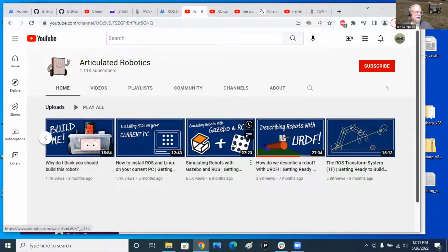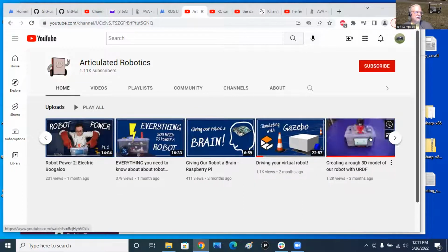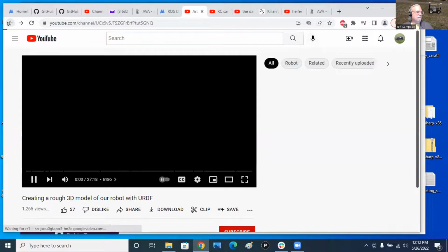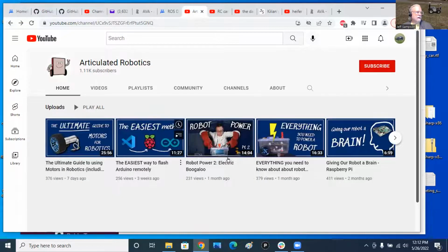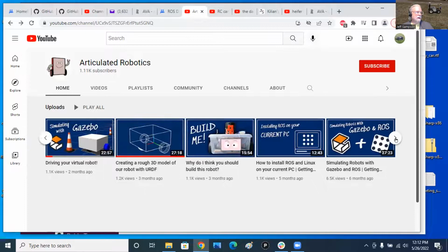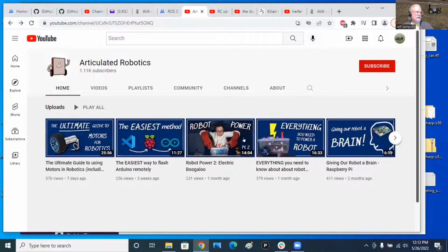He's just building a simple model to go into Gazebo. So he simply built a simple 2-wheel differential drive robot for Gazebo. In the first video, he's talking about how you can view that in RViz. Then in part 2, he pulls that into Gazebo, and he had to change a couple of things to change the color of the vehicle. And he had to add a differential drive Gazebo plug-in to make it drive around. And then since then, he's got some more stuff here.